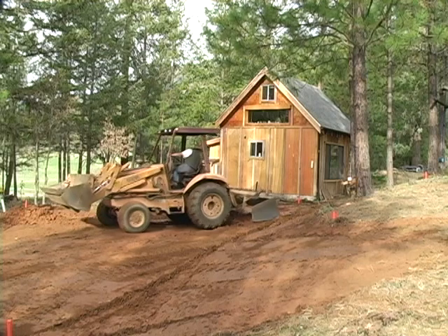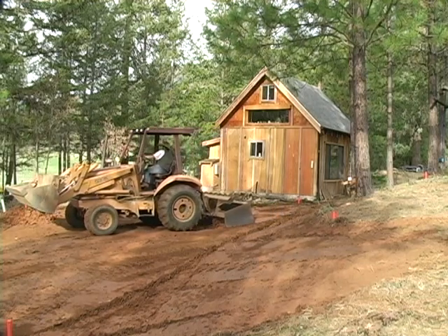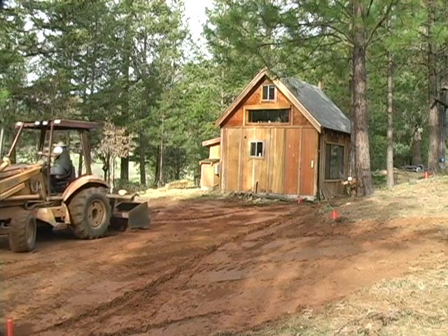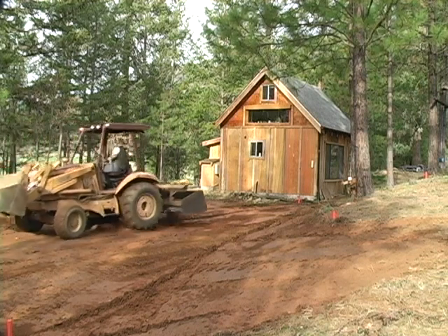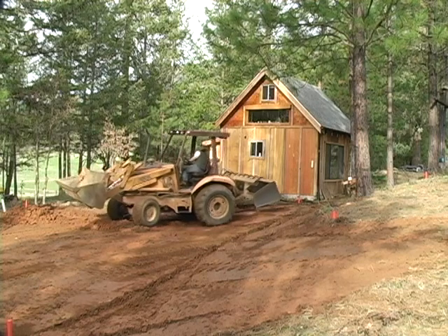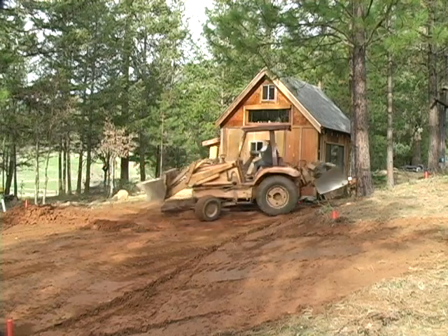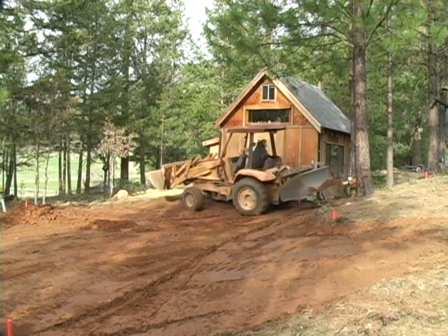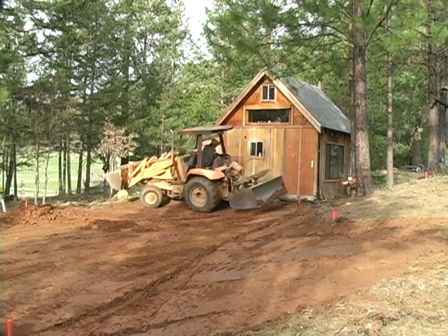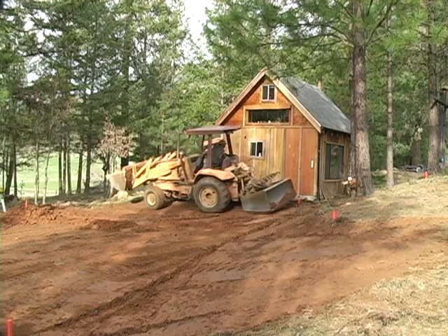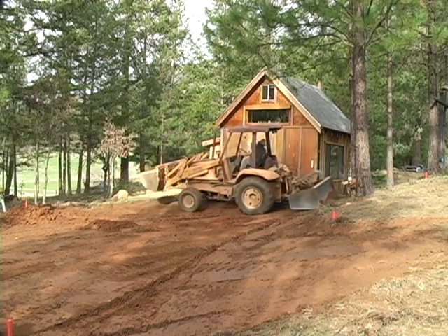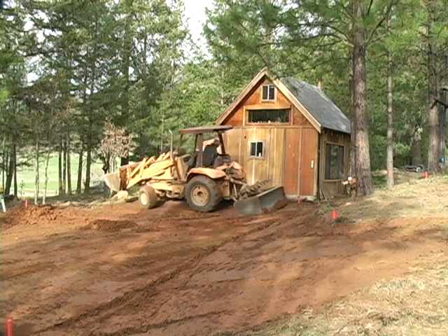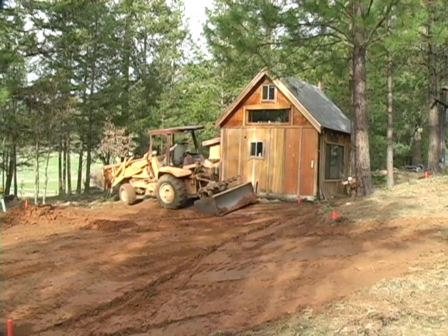Now with all the topsoil removed, you can start to create your actual grade for the slab. So if you've picked a low corner that you want to work back from, you want to grade all of the material out to match that corner. Again, we had some issues here with drainage from the slope coming down, so we're going to try to feather that in as we're creating the slab area. Drainage is a really important issue when you get into foundations and slabs, because if you have water draining directly under the slab, you can actually swell those soils and get some uplift and create cracking in your slab. So be sure to concentrate on that as you're creating your grade.